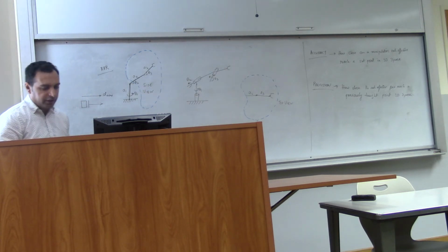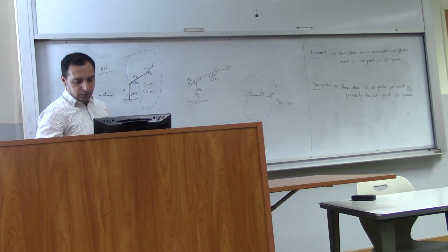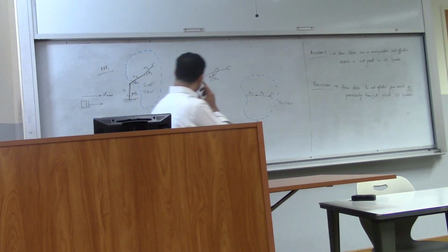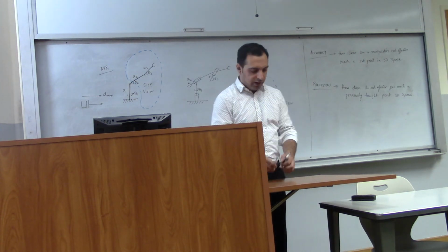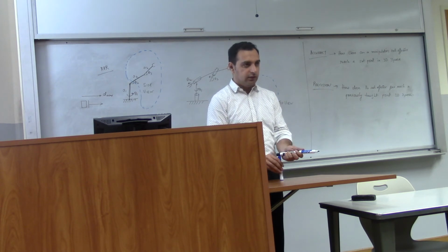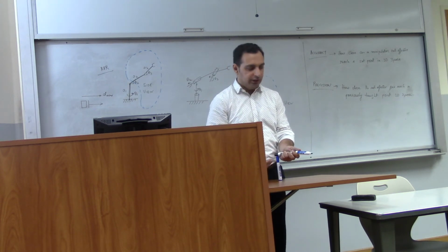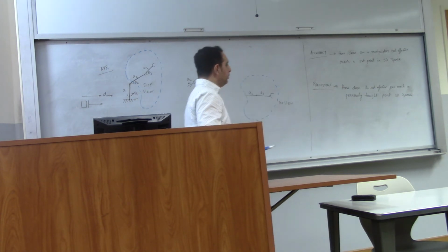Let me give you a very simple configuration, and you can tell me what the workspace will look like. So, Doctor, why is the first link not included in the top view? Okay, so if you have a manipulator like this, these are the two links, and this is the third link, right? When I look from the top, this is going to be a point projection. You don't see this, right? Only when you look from the side will you see this link. From our top view, this will be a point projection.